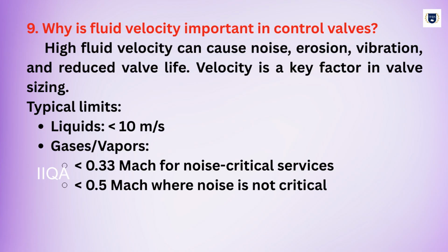Why is fluid velocity important in control valves? High fluid velocity can cause noise, erosion, vibration, and reduced valve life. Velocity is a key factor in valve sizing. Typical limits: liquids, less than 10 meters per second. Gases, vapors, less than 0.33 Mach for noise-critical services. Less than 0.5 Mach where noise is not critical.